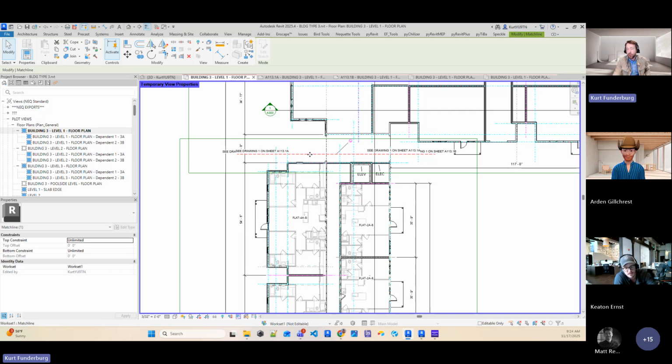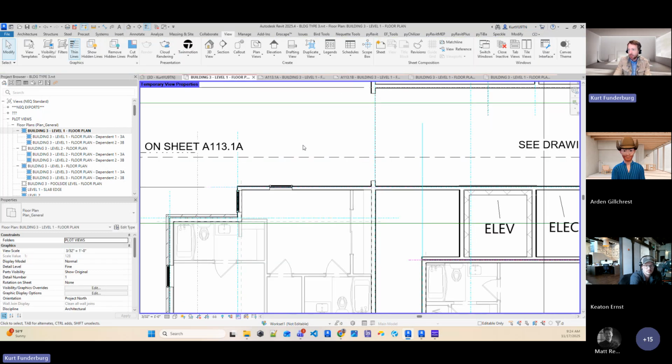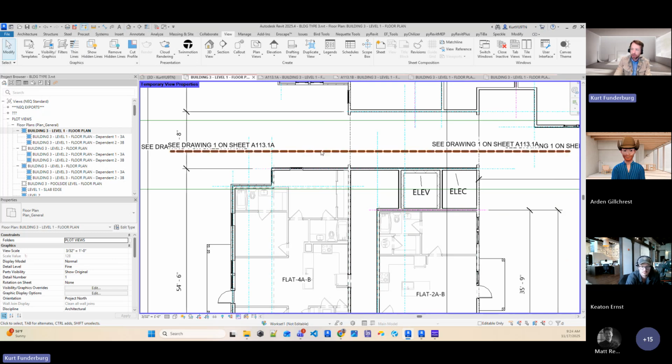If you were using them from the template, something I noticed when I was working in Oxford Farms was I needed to adjust the thickness. A match line is typically a very thick Sharpie-like line to show a visible key that there's more to the building down here, but I'm not showing it to you. If I were to turn on thick lines, it's super thick, and we're just trying to say, hey, the building ends here in this drawing, but there's more down here.